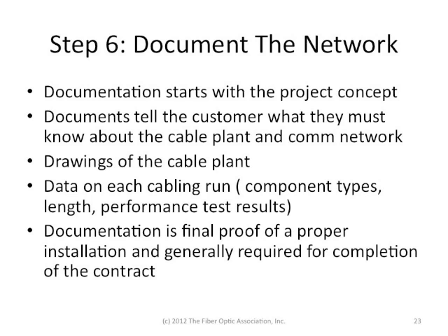Let's talk about documentation. Documentation must start with the project concept. The documents must tell the customer what they must know about the cable plant and the communication network it supports. During the design phase, it'll include drawings. It'll include data on each cabling run, what component types like cables and connectors are used, what the length of the cable runs is, and once the installation is done and the cabling is tested, the documentation will include the test results.